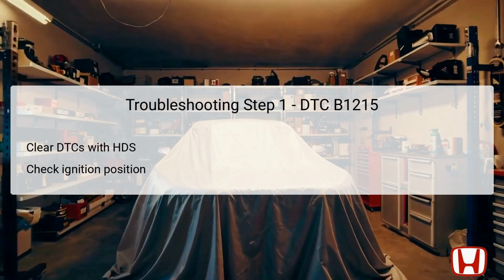After clearing the codes, the technician must turn the ignition switch to the lock position, 0, and then back to the on position, 2. This action resets the system and prepares it for further self-diagnostic functions. It sets the stage for accurate assessments of the climate control unit and ensures that any new issues can be accurately recorded. If DTC B1215 reappears, it prompts further investigation into the circuitry and components involved.